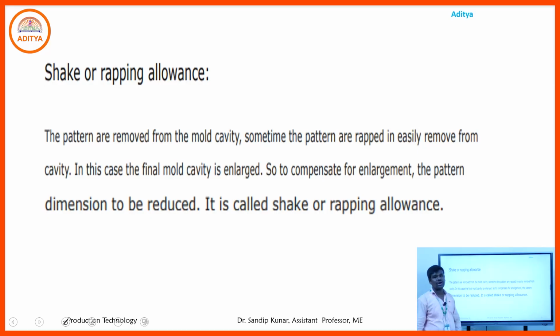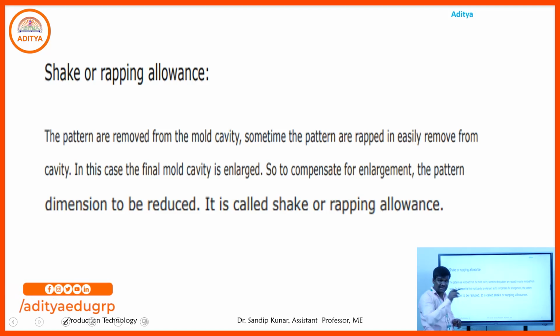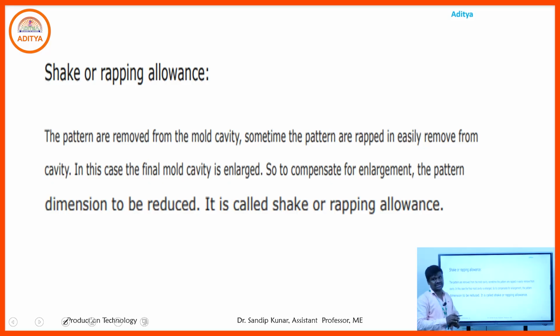Now shaking or rapping allowances. When we want to remove the pattern from the mold cavity, sometimes we shake the molding box. We shake it very carefully, because some extra shape will be generated in that mold cavity, and due to this extra shape we can easily remove the pattern. The inner surface of the mold cavity is not affected. That is called shake or rapping allowance.